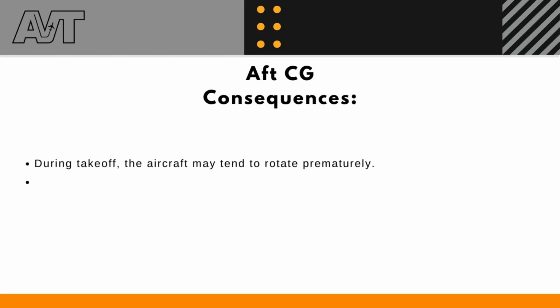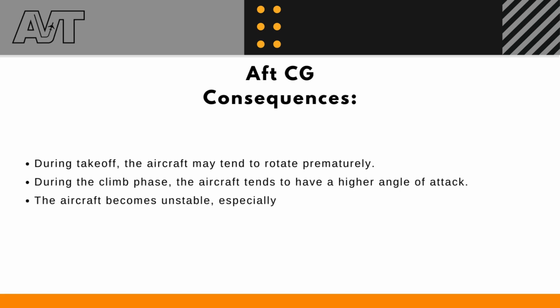Aft CG consequences. During takeoff the aircraft may tend to rotate prematurely. During the climb phase the aircraft tends to have a higher angle of attack. The aircraft becomes unstable, especially at low speeds. Danger of violent stall, lower stall speed but greater difficulty in recovering the aircraft.